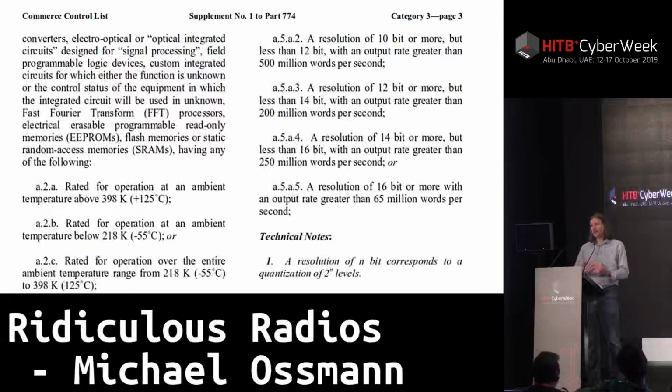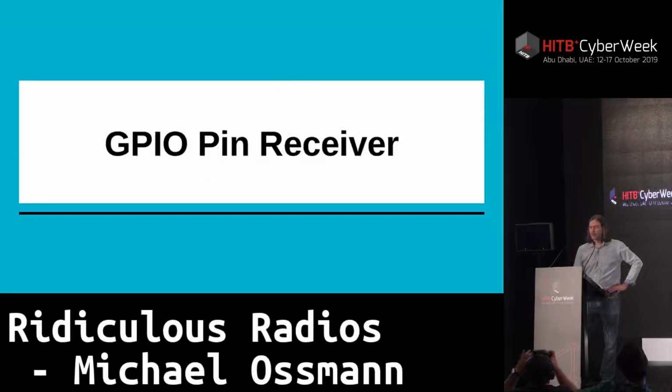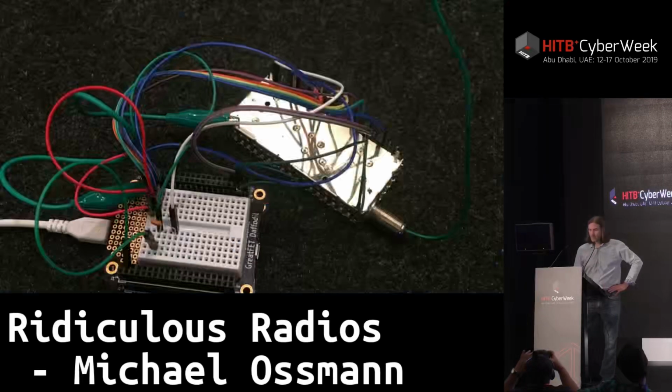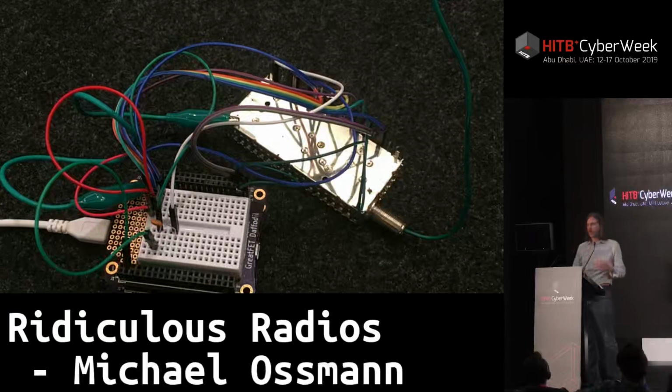So we needed to make sure that we had some analog circuitry in front of our 1-bit receiver that at the very least did some amplification and hopefully some filtering. And we thought, well, where could we get a circuit that has amplification and filtering and maybe mixing that we could just salvage from somewhere? Well, we found one in this metal can here that's connected to my GreatFET. This metal can is a tuner from an old VCR. You might find these also in older televisions.